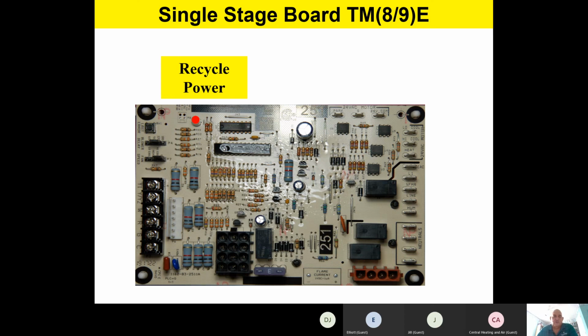its internal electronic check. And so I always like to cycle the power to see if it'll clear itself. And if it doesn't clear itself, if you have a steady on LED, then at that point just replace the board. A steady on LED means the board has failed something internal to its electronic circuitry.